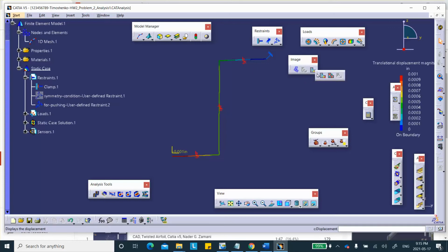The only thing that you can plot is the axial stress, the principal stress, and it's totally useless. You can plot it, and you can see what happens here. All you get is the component of stress in the axis direction. Well, we get it, but that's totally useless. Now, the reason that you cannot plot the von Mises stress, I hope is obvious to some of you. Let me get rid of that first of all. I want to get my displacement plot back.